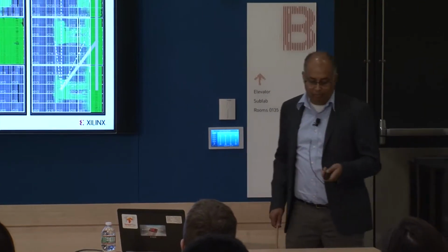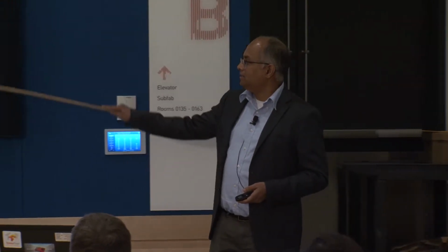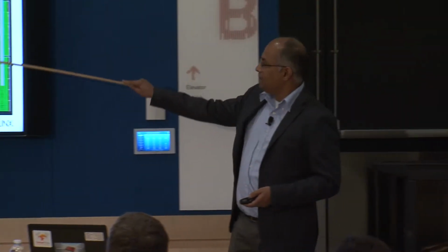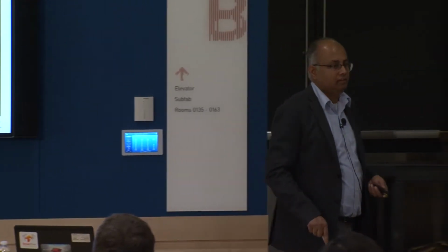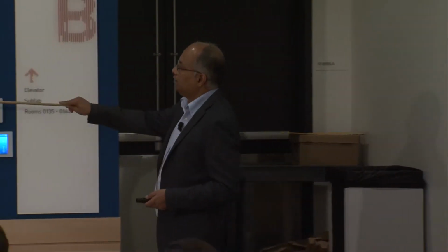This shell is very important because anytime you do your application on an FPGA accelerator, you should be aware that some part of the FPGA is not available to you. If some of you have used Amazon F1, you will see that they take pretty much this much of the region for whatever they are doing. How people deploy FPGA in a cloud environment depends on what else they want to do, but fundamentally, you won't have 100% of the FPGA available. What we recommend for ML applications is to use a thinner shell so that you have most of the other logic available.